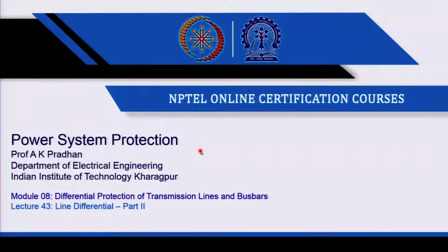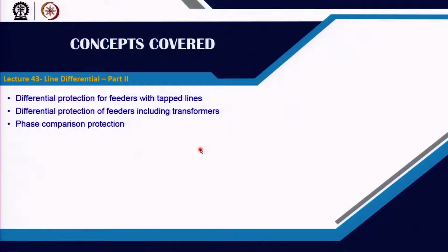Welcome to NPTEL course on power system protection. We are continuing with line differential protection. In this lecture, our focus will be on transmission line or any feeder having tapped lines, differential protection that includes also a transformer, and at the end we will go for the phase comparison protection, which also has the communication support.